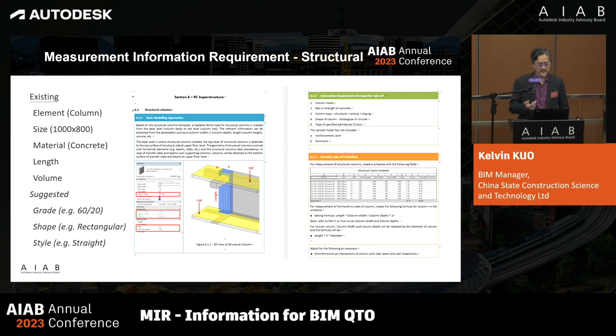Okay, for example, in the concrete works, we need to create structural models. We have the framing models according to walls, beams, slabs, columns, which are the most basic components that we need to create in the structural models. But we should have something that we have to mention. The simplest example should be the concrete grade. Actually, the modeler just creates a column, just creates a wall, but doesn't mention the concrete grade, because the concrete grade always refers to the general specifications on page 1 of the structural drawing sets.